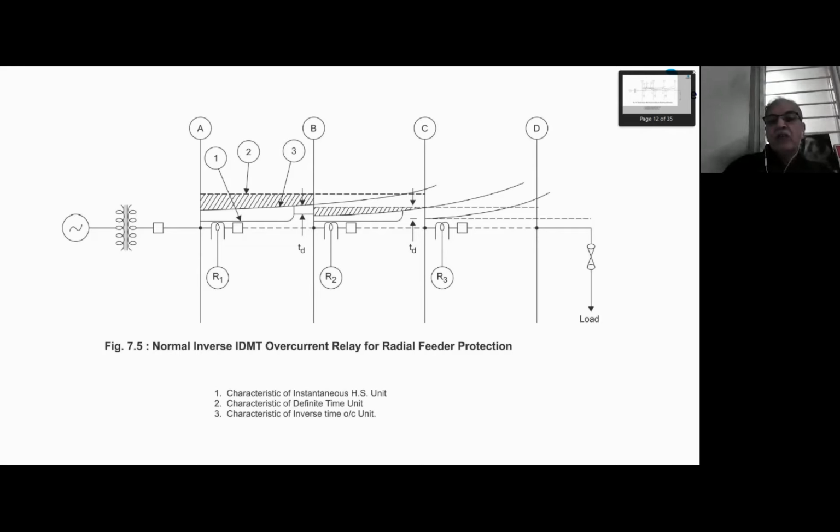There is a discriminative time margin TD, and I have to maintain that margin. What is the value of that discriminative time margin TD? That is variable. Variable means people are using different values in research papers, with reference to different kinds of relays, better relays, more accurate relays, better breakers, etc. But how to arrive at or calculate that time discriminative margin TD cannot be discussed today in